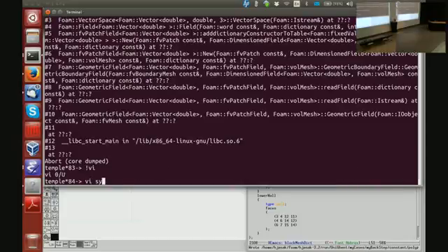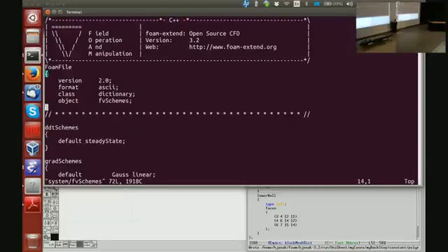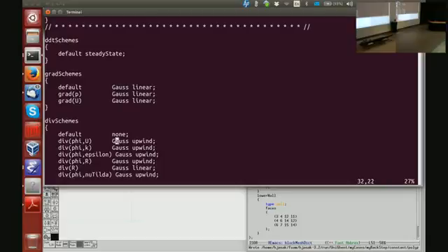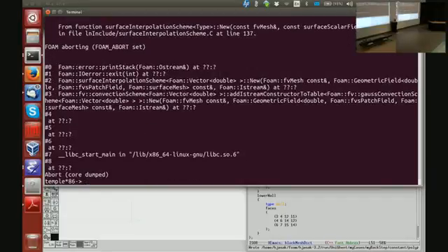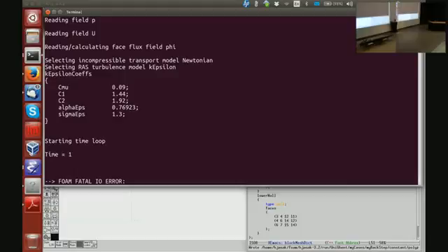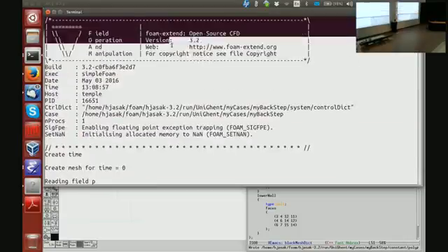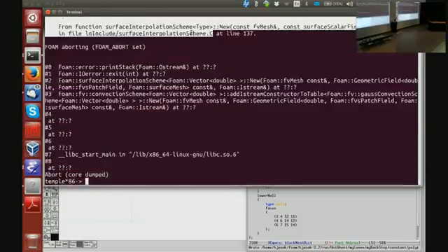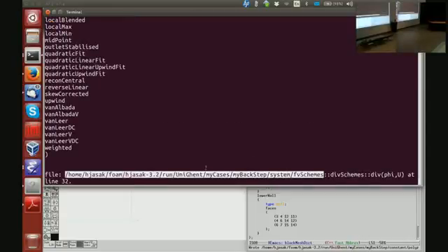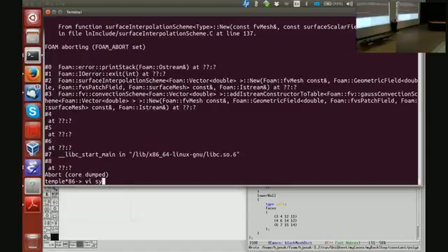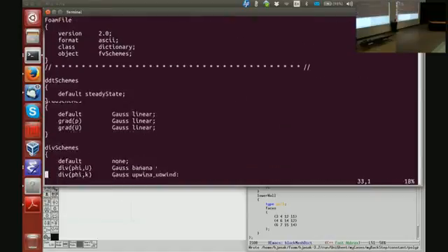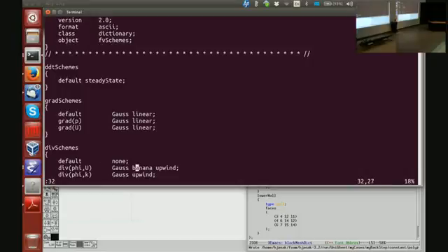Okay, now let's do something more complicated. fvSchemes, default scheme, now it says, FOAM fatal I/O error, unknown discretization scheme banana, valid options are blah blah blah, in file system/fvSchemes, divSchemes, div(phi,U) at line 32. Okay? Line 32, and here's my banana.